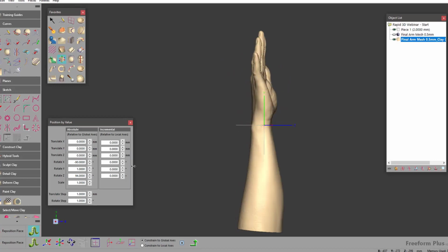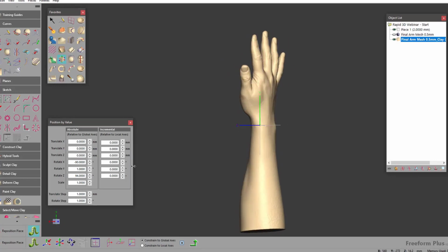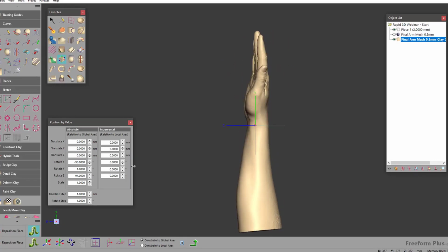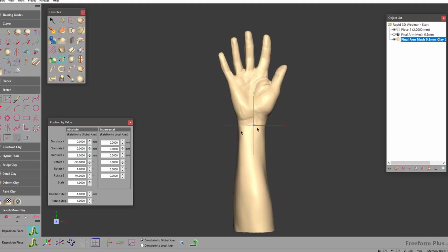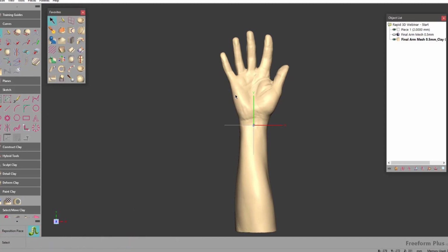And then what I like to do is I use the arrow keys and kind of rotate around the part and make sure that it is where I want it to be. So if you see I want to bump it forward a little bit, I can do that and position it. I like to position it here, and you'll see why in a minute, that I'm going to put my 0 point at that location. So we'll just come in and bump the X there, right there. So I'm going to go ahead and get out of that tool.